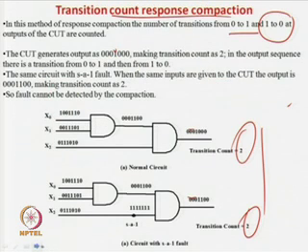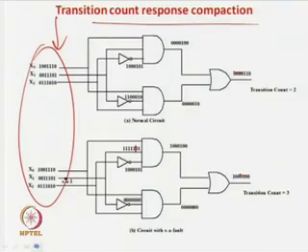By looking at all these things, you have to decide which test patterns to apply and which compaction technique to use, and depending on the test patterns you apply, you can decide on your characteristic polynomial and your seed. That is why design of a BIST is a challenging problem: you can appropriately cover most of the faults, and at the same time do that very quickly using the initial set of patterns determined from the seed of a standard or modular LFSR. That is a very important step.